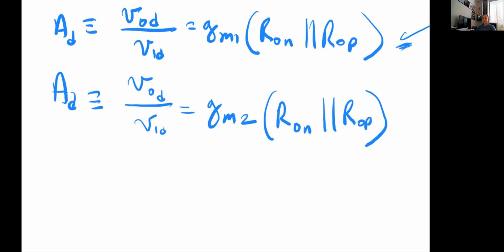I don't want to amplify voltages that are common to both terminals. And this is very important and very nice to have, because you can imagine that if you have noise in the system and you assume that the noise is common to everywhere, then you can have a high noise environment. And if your amplifier has a good common mode rejection, that noise is not going to be amplified. It's going to be rejected because it's common mode.